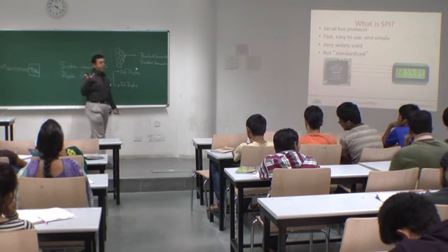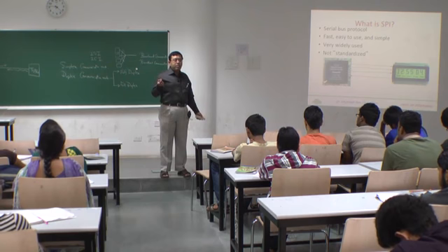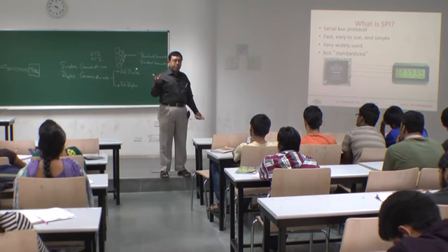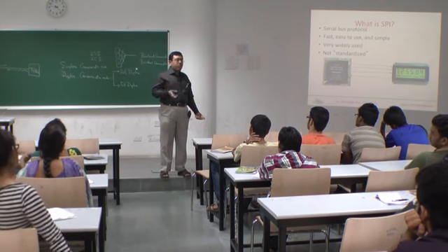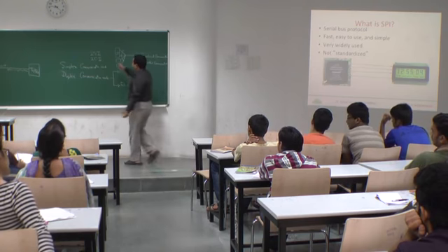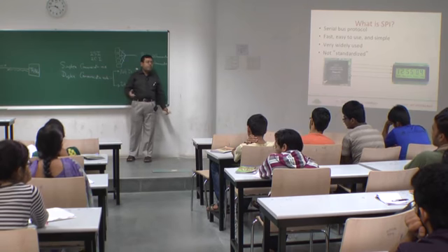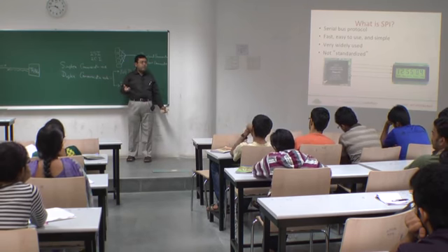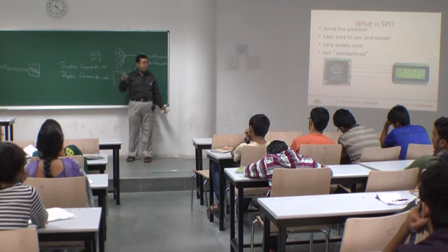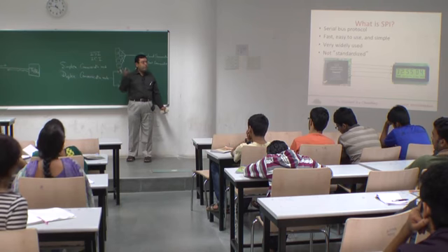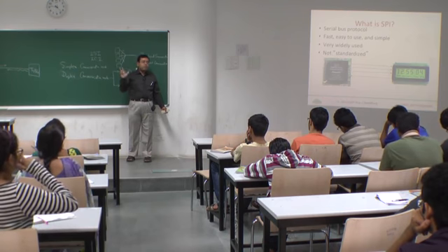So, in telephones, when you talk to another person over the telephone, frequently you hear some other conversation taking place over the telephone, which is not your conversation, and we call it a crosstalk. The crosstalk is typically an outcome of this ISI or inter-symbol interference. So, when the inter-symbol interference becomes considerable, you cannot intelligibly distinguish between your voice and the voice of some other conversation taking place, and you hear the noise and the sound of the other conversation over your same channel.